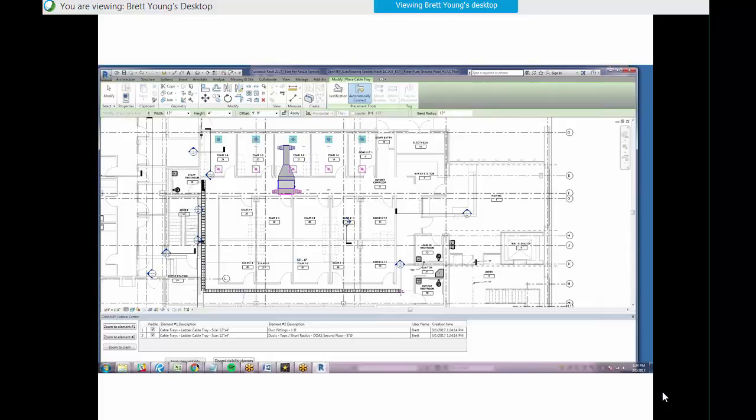But if you're trying to say, I want to dynamically change my ceiling height and maybe run that kind of scoring like you were doing in your routing, and say, if I'm lowering the ceiling height, it does X, Y, and Z, and that X, Y, and Z is something I have in my Dynamo script that's being informed by quantity of clashes and size of clash. So maybe I'm thinking of it wrong. Maybe what you really want is to use Dynamo much like Ben does and do a test fit of that cable tray in every part of the plenum. You can do 1,000 times per plenum. Possibly, yeah. And what you really want is a list of clashes that come back whenever you go and run that. So, okay.